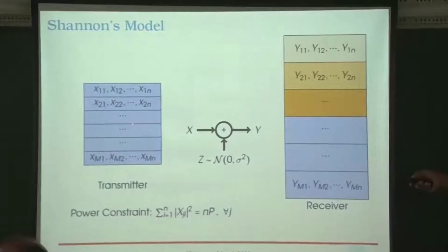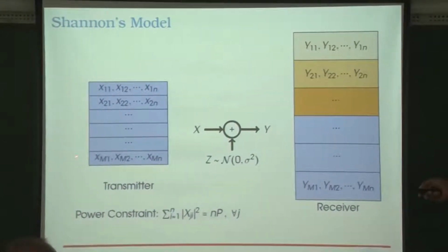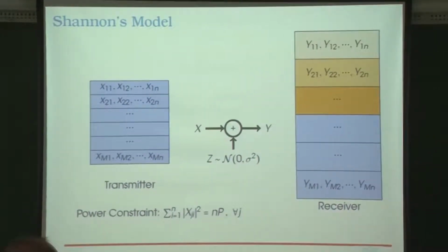In general it's a MAP decoder, right? But here, since we assume in information theory that we have uniform likelihood on the messages, maximum likelihood is the best estimator, and because it's Gaussian, the maximum likelihood simply breaks down to what is known as minimum distance decoding. You take the y and find the x which is closest to it, and then declare that is the message. That's the best decoding, or you cannot beat it. That gives you the minimal error probability.